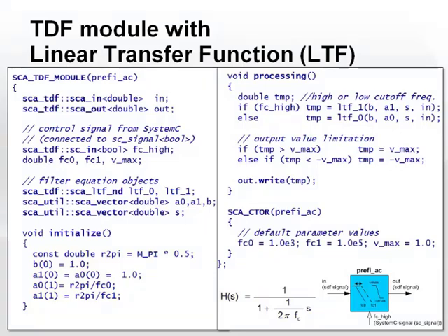And then, in the processing function, according to the value of the Boolean discrete event input here, you will use this kind of construct to perform the filtering and the call to the linear transfer function. Here, in is the input, S is the state of the construct, and here are the denominator and the numerator of this LTF construct.